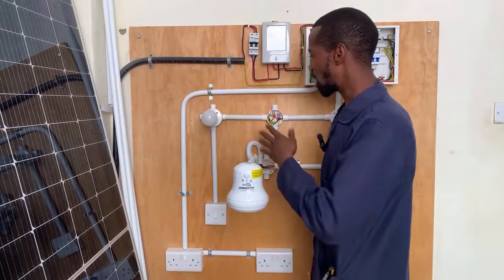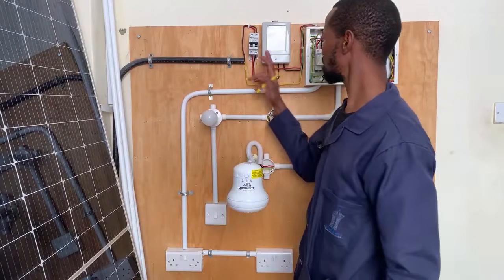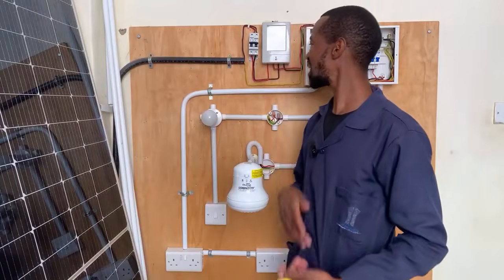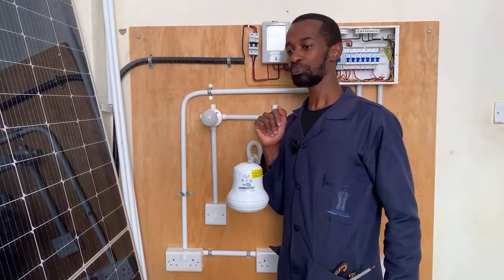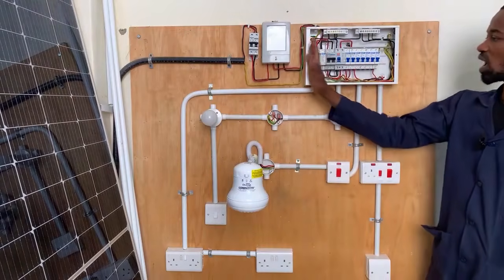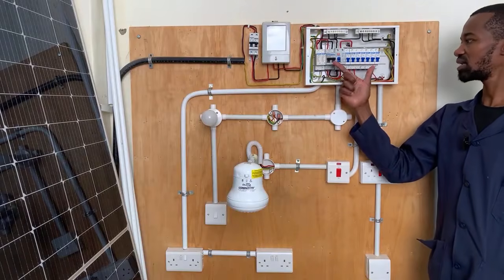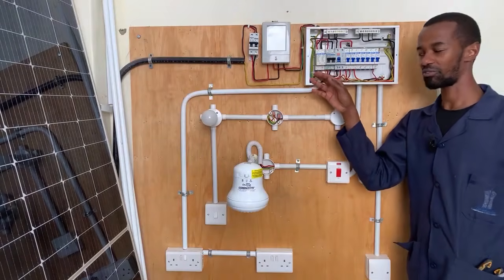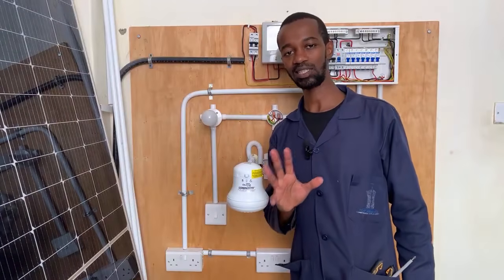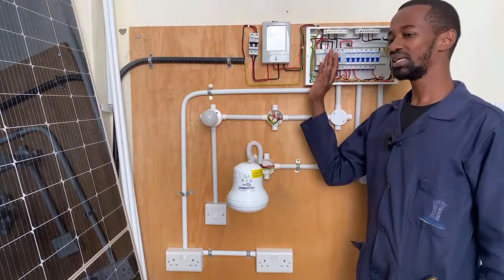Now, when it comes to these, we have an MCCB, right, that is right here. This acts as the main switch or the isolator. It is at the meter box simply because it is supposed to isolate the entire installation. When you have visited a customer and there is a problem in the house, let's say a very big issue, maybe even fire, this is the safest point for you to isolate electricity. Let us isolate electricity in case there is flooding or fire, so that we can deal with other issues.